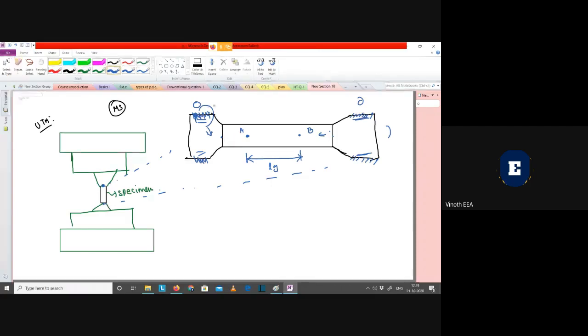Okay. So here, this is what grip is. I'm just going to connect this grip here. Okay, right. So what is the procedure? Simple. See, in this specimen, I will be attaching something called an extensometer, or else I will be attaching strain gauges, mostly electrical resistance strain gauges only. If you had done your experiment in your college SOM, strength of materials lab, you would have done this mostly. So either electrical resistance strain gauge or extensometer will be there.